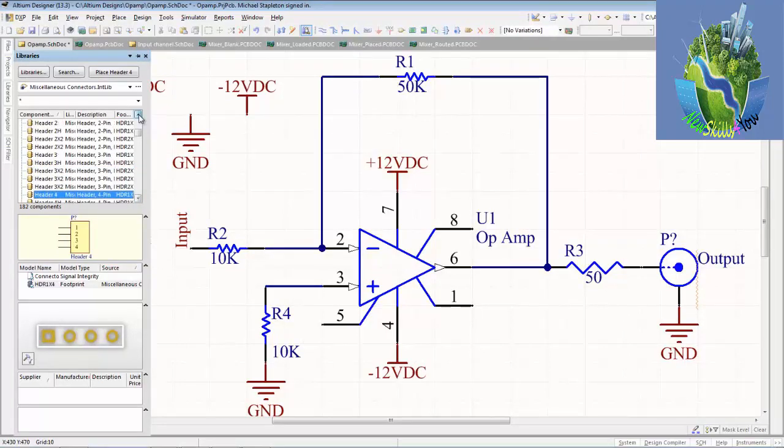You'll notice that when I look at my 2-pin header or a 3-pin header, there's a schematic symbol, there's the 3 holes, there's also a 3H. Now the difference is, and we'll look at this one, here's my 3 connections on my schematic, here's the 3 holes in the board where I'm going to solder my parts, but you'll see that I have this drawing here. The reason the drawing is there is, unlike the standard header 3, the header 3H, the pins come out, they go up vertically a little bit, and then they turn 90 degrees and go horizontal. So you'll see that there's a space drawn on my board to show how those pins will come up and bend over. Let's use the horizontal placing, right, the header 3.